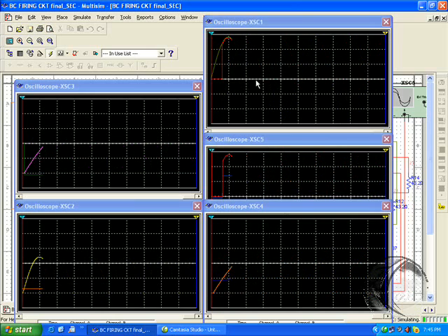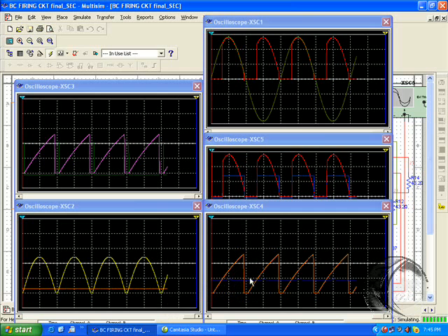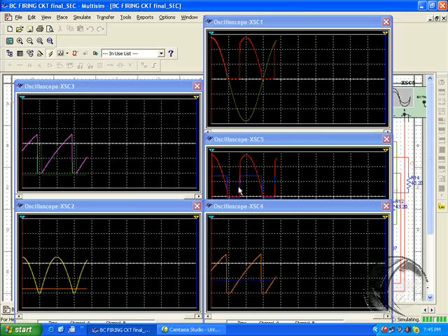So what in practice we do, this level change which is happening, is actually controlled from a feedback circuit, and that feedback maintains this at a particular level. If the voltage goes on increasing, this level will go on rising. When this goes on rising, this will be narrow, and this will be getting more delayed.